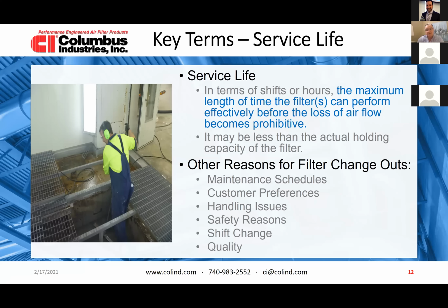So first, when you reach a point where operating the spray booths becomes prohibitive, in other words, where the regulatory levels of airflow go below the minimum level of airflow, you cannot operate anymore, and you need to change your filters to get your airflow moving and to get to where you have safety parameters, especially if you have operators in there. There's a minimum airflow that you need to have in there.